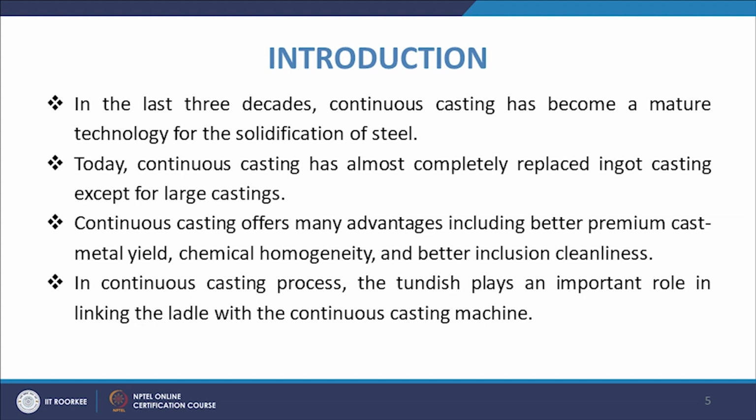It offers many advantages, including better premium cast metal yield, chemical homogeneity and better inclusion cleanliness. As far as better premium cast metal yield is concerned, in normal conventional casting the casting yield is not very high because of the removal of gates and risers and other things.